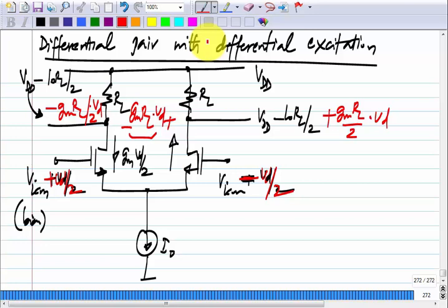But we started off saying that we want to make an op amp. That means that we have to shoot for much higher gains than this. Here we may get 10 at most or something. So, what is the technique to get a much higher gain? What did we do? Yeah, but cascading is fine, but if you have a gain of 5 from this, to get to 1000 you have to cascade so many stages, and then you have to deal with stabilization of that complicated feedback, right. What is the first thing? You try to get as much gain as possible from each stage, and then you cascade as many as you require. Okay. Active load.